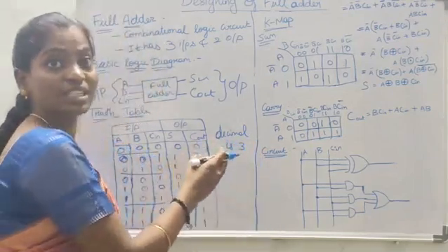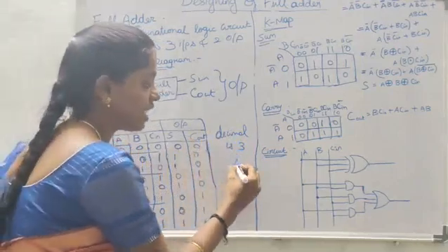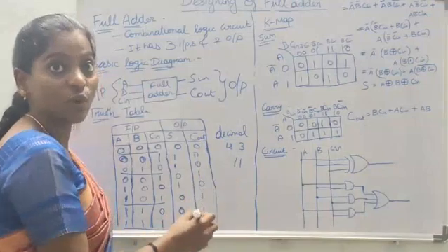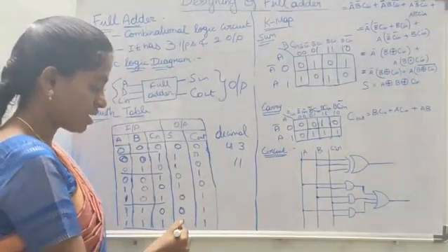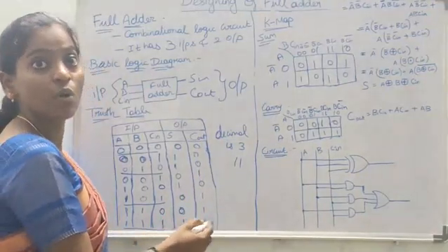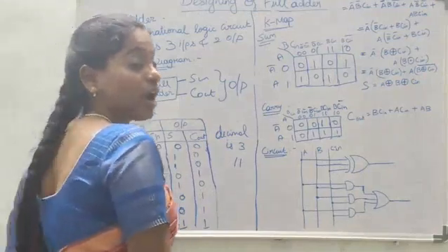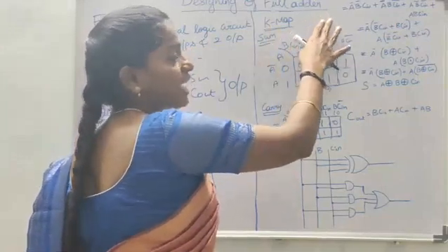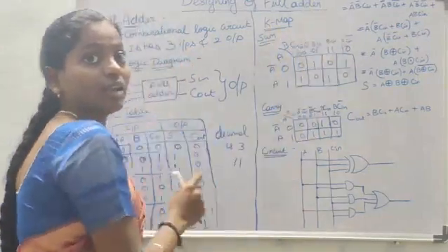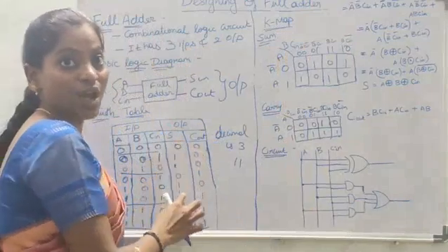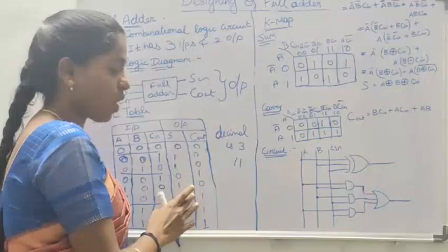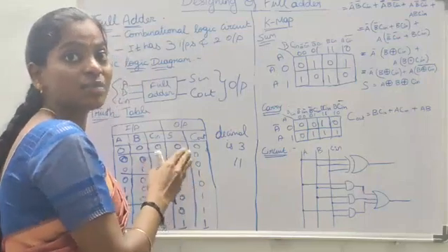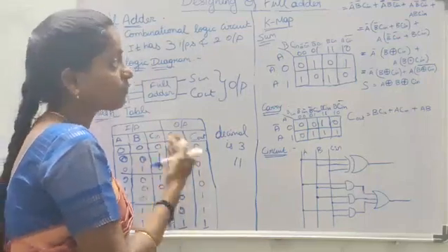The binary representation of decimal 3 is 11. Therefore, the sum becomes 1 and the carry out becomes 1. Now, using a K-map, we generate the expression. Let us observe the sum column. The sum is 1 when an odd number of the inputs are 1.